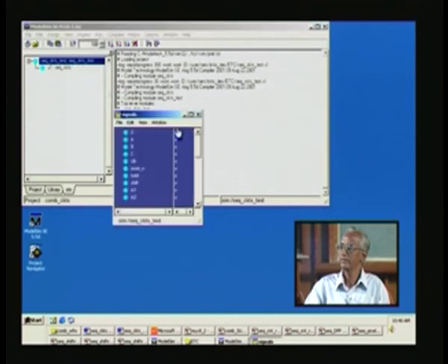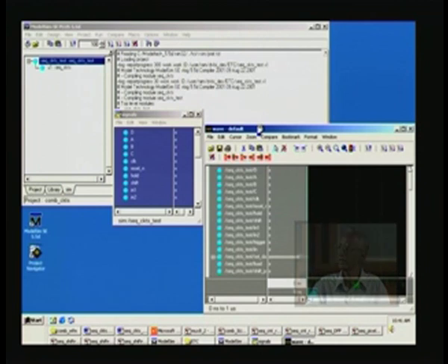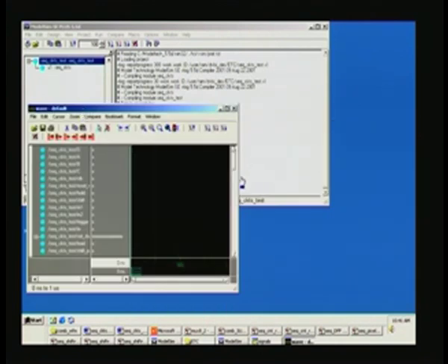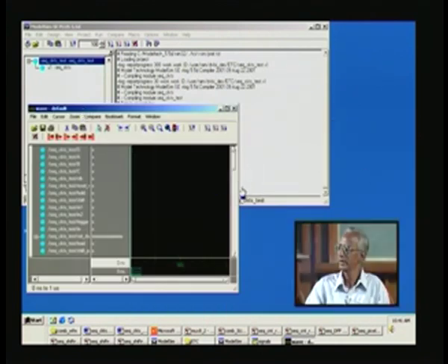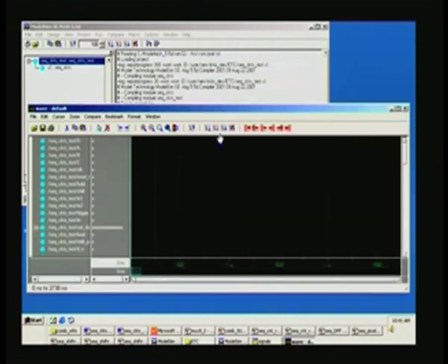and you have the signal window open, and you can see some of the inputs here partially. You can see all the IOs listed here, and you can get it as a waveform. Go to view, then signals in design, and here it opens the waveform window, and let us run this. For run, this is the command here, run all is there.